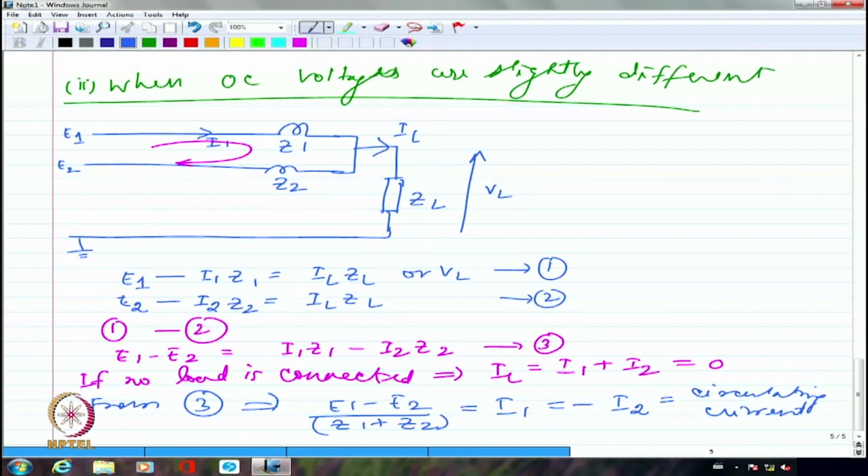If it is a lot of current, that means the thickness of the windings will be very, very high. If the thickness of the winding is high, obviously I'm going to have the resistance to be smaller. So if you look at a 1 kVA transformer in the lab vis-a-vis a 100 kVA transformer in a substation, you would see invariably that the 100 kVA transformer in the substation will have much smaller actual ohmic impedance.